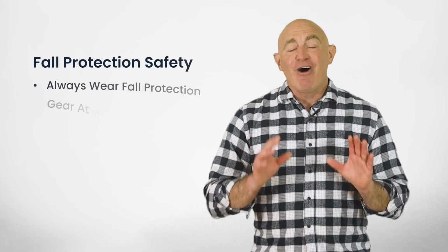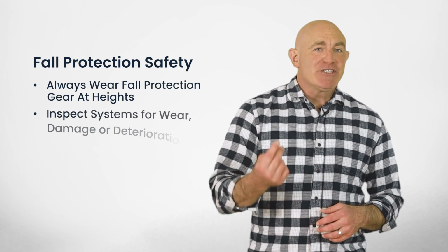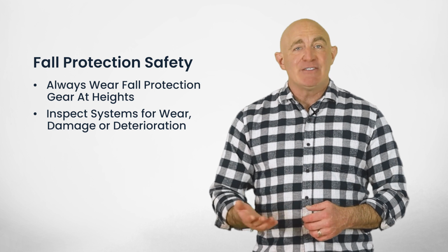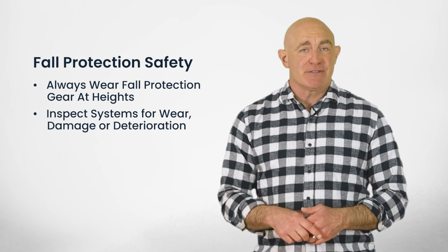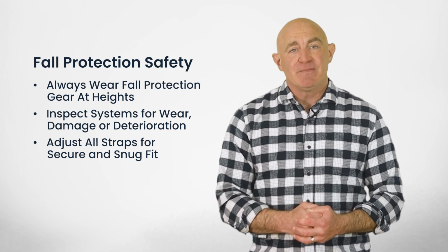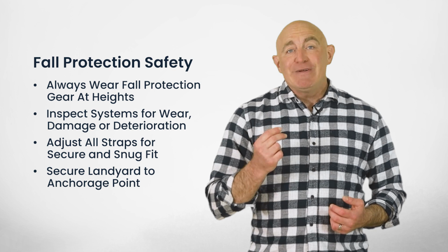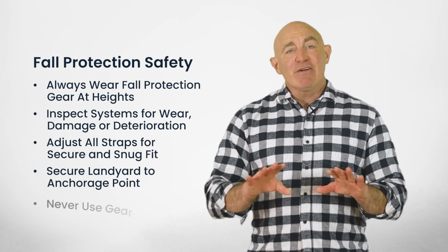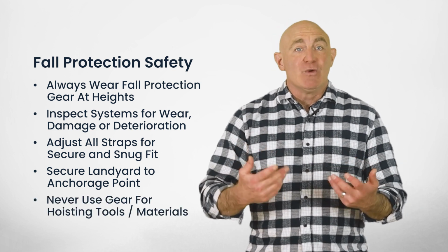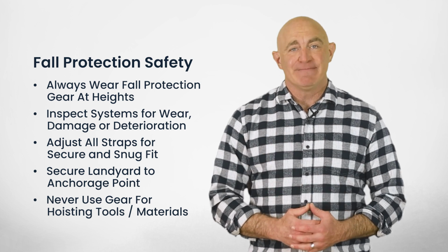So to stay safe, always wear your fall protection gear when working at heights. Inspect your systems for wear, damage, or deterioration before each use. Adjust all straps to ensure a secure and snug fit. Secure your lanyard or lifeline to a sturdy approved anchorage point. And never use your gear for hoisting tools or materials. It's designed for human use only.